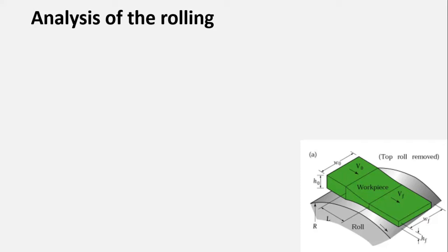As we have discussed in the last chapter, in the deformation process or the metal forming process, we primarily concentrate on the true strain, because that is what is used to calculate the flow stress. And what was the flow stress? The stress that is required to continue the deformation. So in the rolling operation, there is a requirement to continue the deformation while performing the rolling operation.